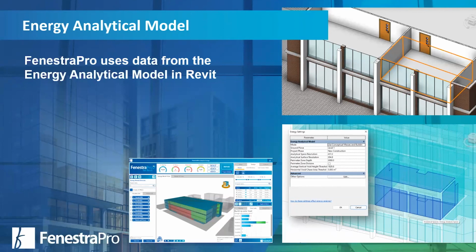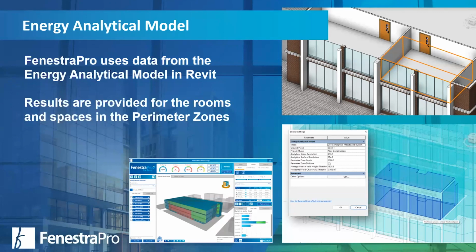So it's native to Revit, it's built within the Revit model, and what it does is it basically looks at the Revit external walls, internal walls, what they call room bounding elements, what's a roof and what's a floor, etc. And it creates this understanding, I guess, this piece of data that understands the analytical spaces, in other words, the rooms, the conditioned rooms or conditioned spaces within that building, and the associated external surfaces, or what they call the analytical surfaces to that model, right? So that's a really great way of breaking that data down.